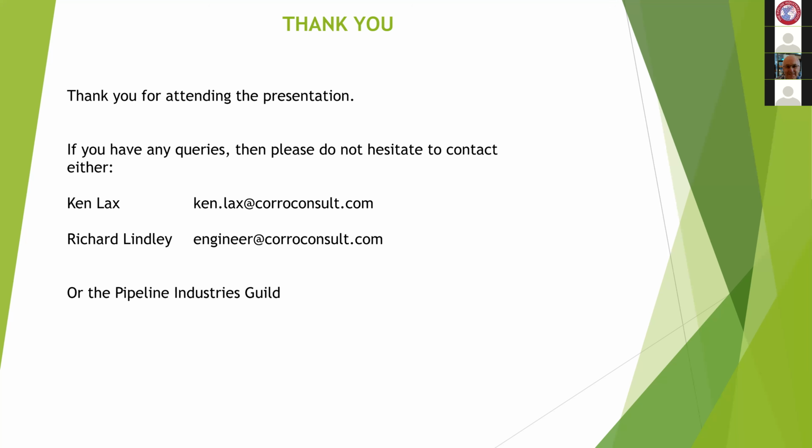Okay, thank you. The last question is anodic protection. Glass coatings are commonly used for CP in offshore applications. Are you saying that the quality of coatings available today negates the need for anodes? Again, a very good question. I think you mean cathodic protection plus coatings are commonly used. And I would say no, because we simply cannot guarantee a high quality coating for the entire length of the pipe. We can only do it for short sections.